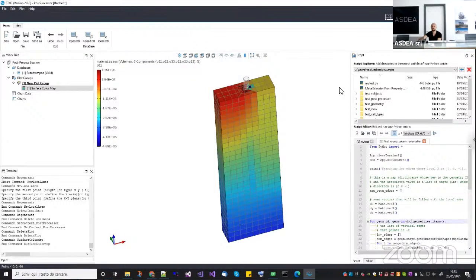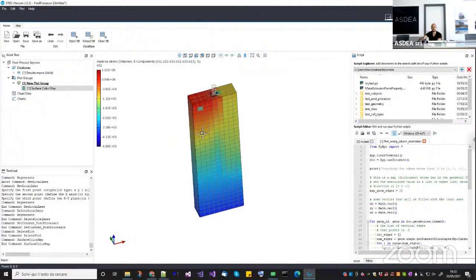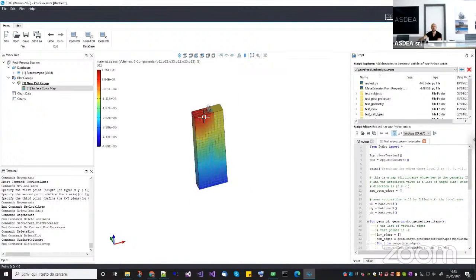Yes, in the previous webinar on soil structure interaction, I used the Lysmer-Kuhlemeyer properties of a bedrock. If you want to use the Lysmer-Kuhlemeyer property of the same domain, so if, for example, you don't do a cut at the level of the bedrock, but there is the same soil domain, even in the part that you didn't model, you simply apply the Lysmer-Kuhlemeyer related to the velocities of this soil medium. Okay, so that is the same. You simply have to change the Lysmer-Kuhlemeyer properties.